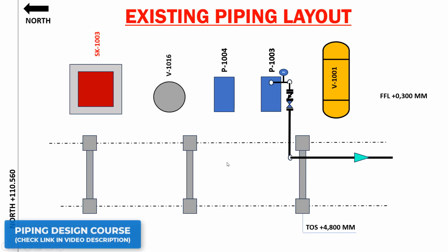Okay, now let's start with it. What I'm showing over here, you can see the nozzles. This is what I was highlighting. See, when it comes to vendor related items, the internal designs will be taken care of by the vendor. So you don't have to do it, but your external designs are your part, which is the piping. So here this nozzle orientation is important. Since you are interested only in the discharge nozzle, your discharge nozzle orientation is really important, but you also have a concern with the suction nozzle.